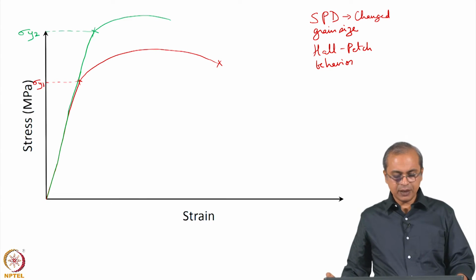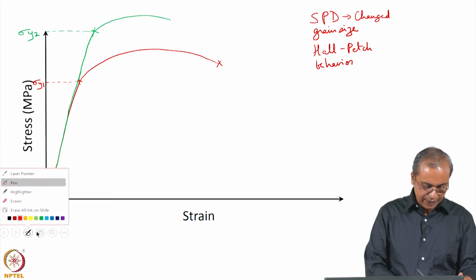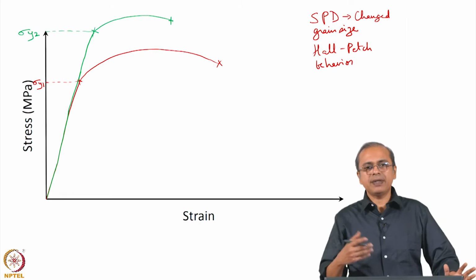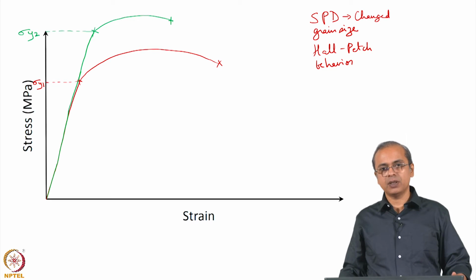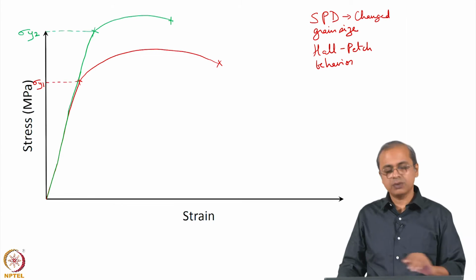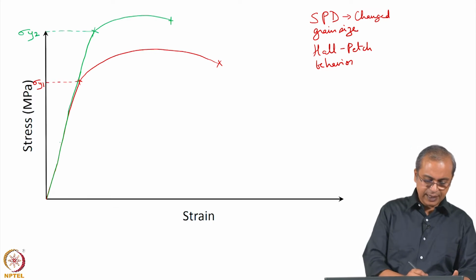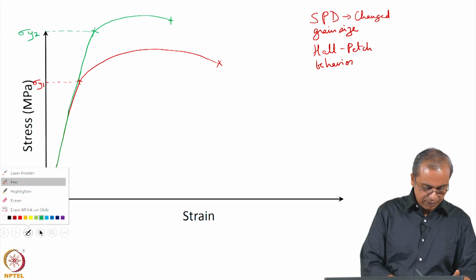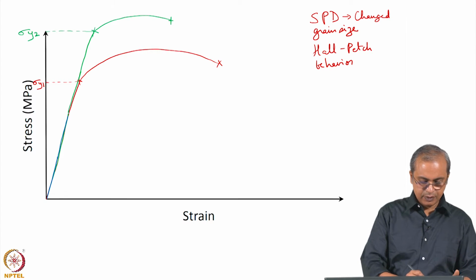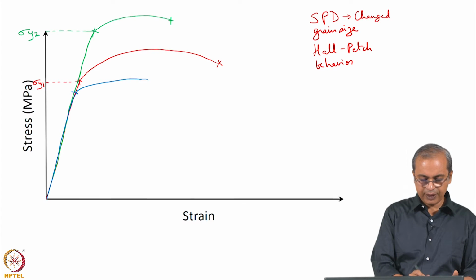Okay, and so that is how the strength will change, and the amount of plastic deformation that it may undergo before failure may change. It may not necessarily be the same. Usually, when the strength goes up to some degree, the ductility comes down. These things are not absolute, but this is the general trend that you tend to see, and this is what you are likely to see. In case the inverse Hall-Petch relationship is in vogue, you may see that it actually deviates from linearity sooner. So, you may see a behavior that begins to look like that. So, you may have a lower sigma y.